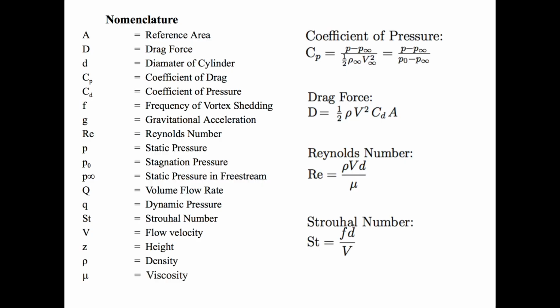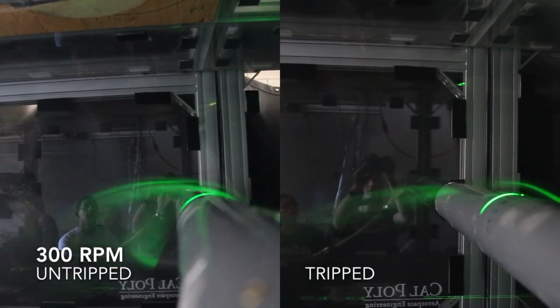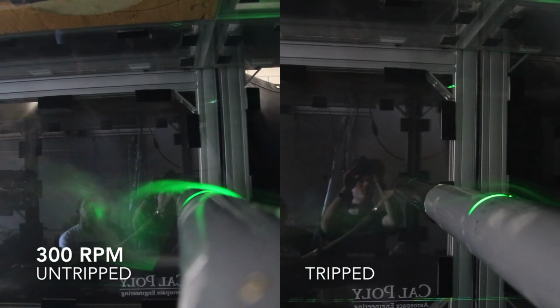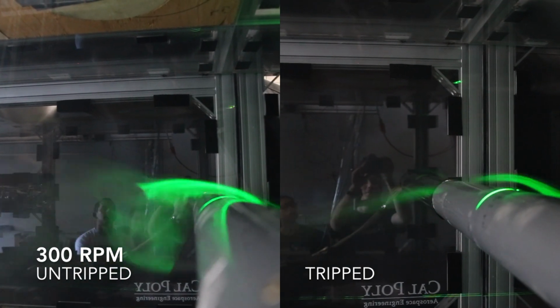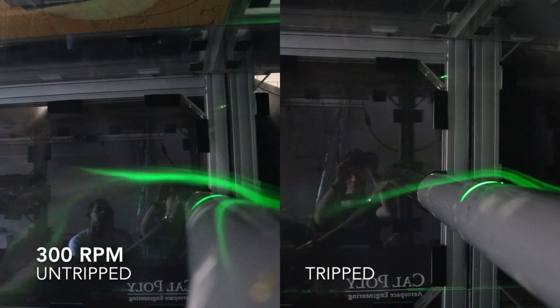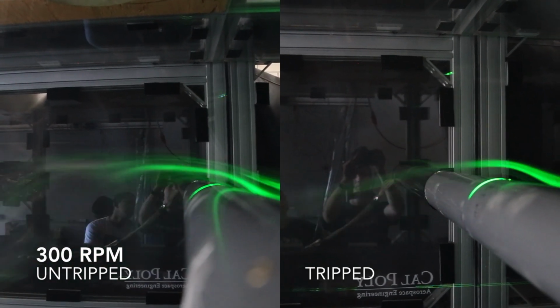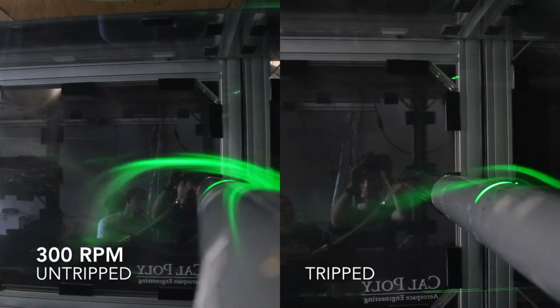Alongside this, analysis of the pressure port data supports these conclusions and gives more insight into how the flow behaves along different areas of the cylinder. In conclusion, flow will stay most connected to a cylinder at higher wind speeds and by energizing the flow via surface roughness. Further tests may be conducted to find the best materials and areas on the cylinder to place these trip strips to most reduce vortex shedding.